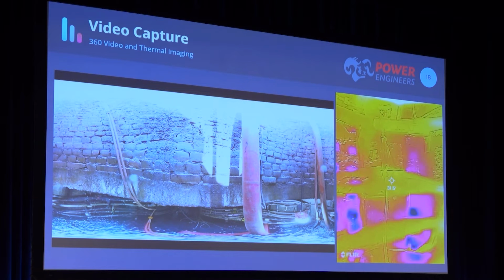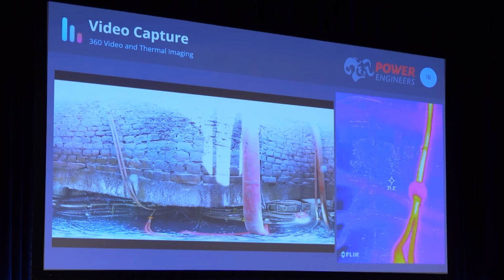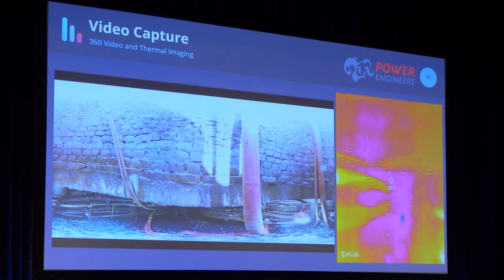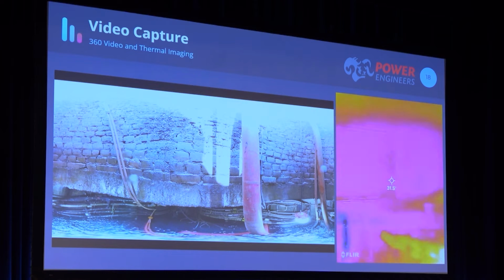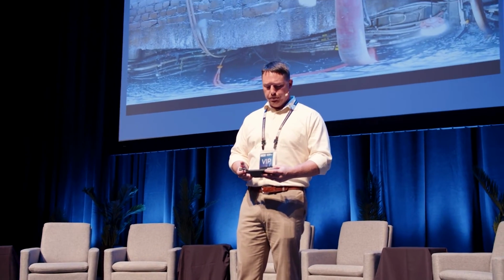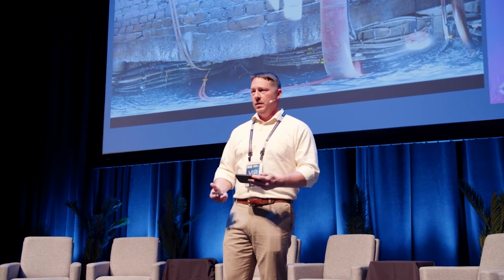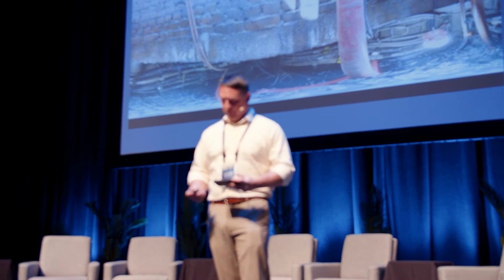Also, you need to adhere to the local standards, jurisdictional standards, and in the case of the scan you see here, we had to get the police to help control traffic, which seemed to be a specific use case because that wasn't the case on all the projects I've been on. And then using non-conductive equipment like dielectric boots, arc-rated clothing, and things like that. All important things to consider.